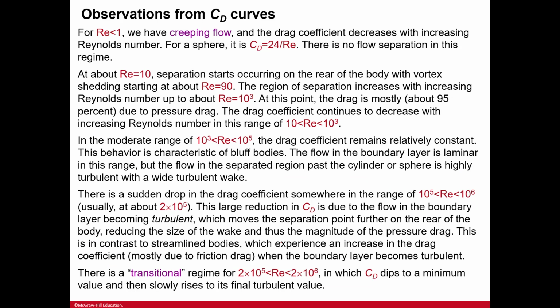These are some of the observations from those curves. For Reynolds numbers less than 1, we have the creeping flow, right? Low, slow. The drag coefficient decreases with increasing Reynolds numbers. For a sphere, this is it. There's no flow separation in this regime.